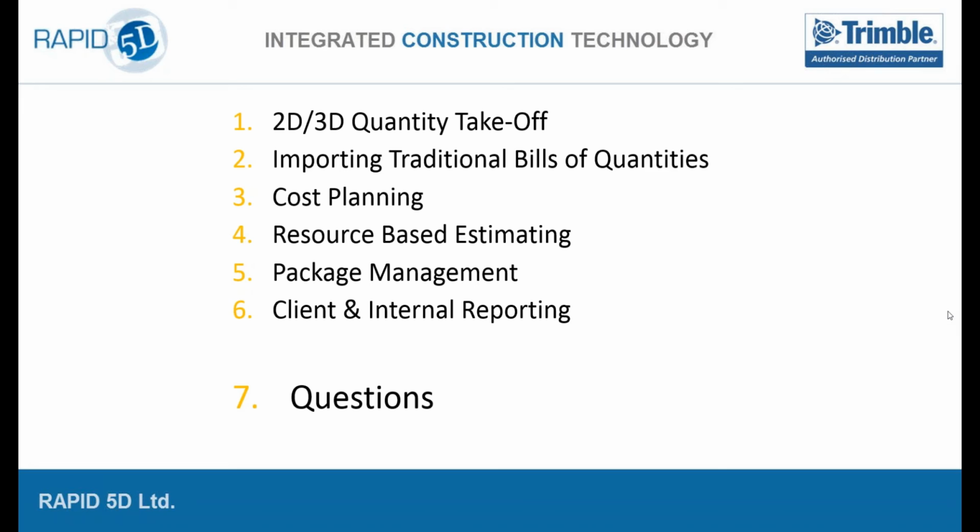If I've constructed a slab and all my method is under that slab, next time I produce a slab I know exactly which method I need to use. Whereas the problem with an SMM7 style bill is that to produce that slab, the concrete could be on page 2 and the formwork on page 5, so gathering all that data up and reusing it can become tricky, so we tend to recommend NRM1.